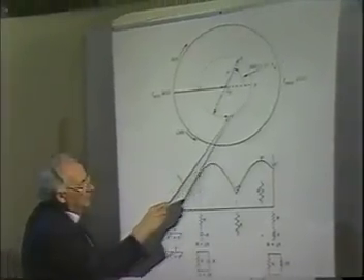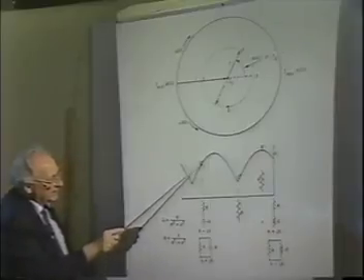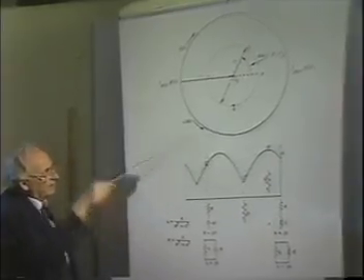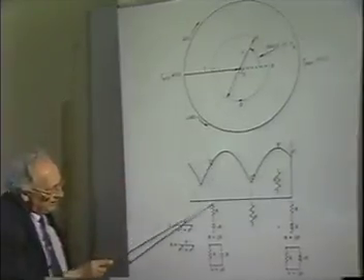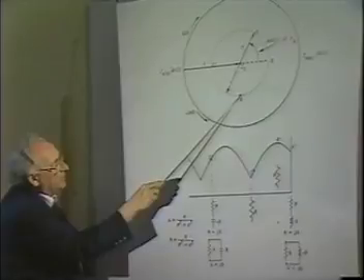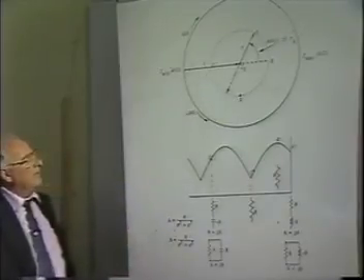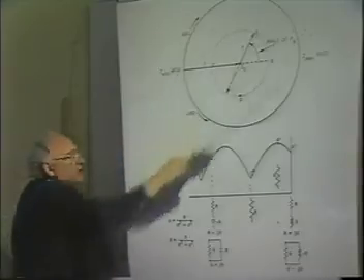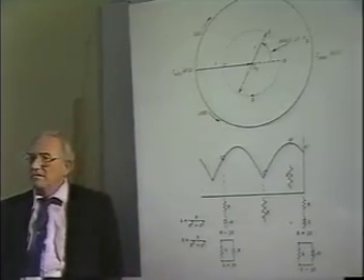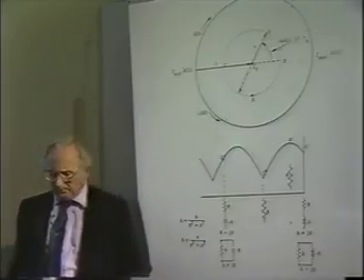Then you go all around the line, and here's D. In other words, you've gone along the line, back around the chart, and you have a resistor and a capacitor at this point here. Go back here, you have pure resistance, Z min. If you travel this way, clockwise, you're always going toward the generator. Back here, counterclockwise, you're going toward the load.